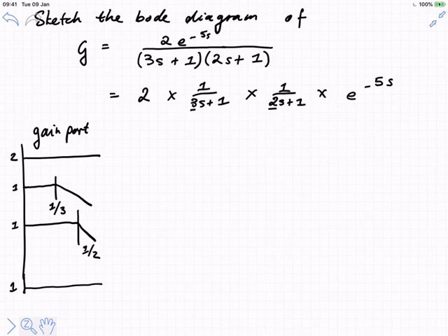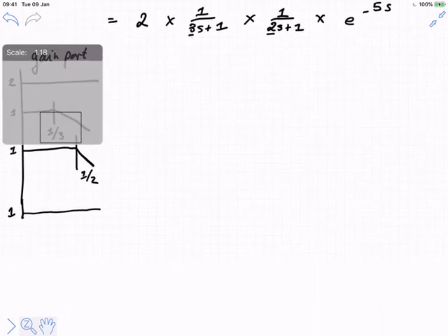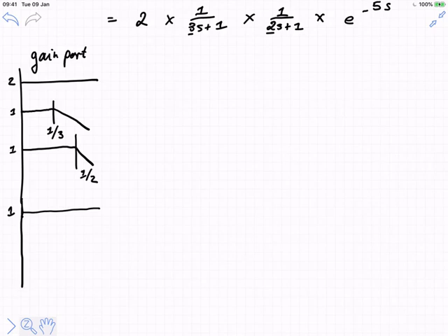Because of that, we can just add all of these things together. Again, I'm expecting you to add them mentally in your mind so that you end up with a combined gain part that is, now again, when we're talking about these, you've got to reason logarithmically, right? So the gain part will be at 2. Does that make sense? The shape is adding together. Another way of thinking about this is like I'm taking the log and then adding all those things in the logged domain. So these unity gains don't have an effect, right? So the overall gain will be 2.